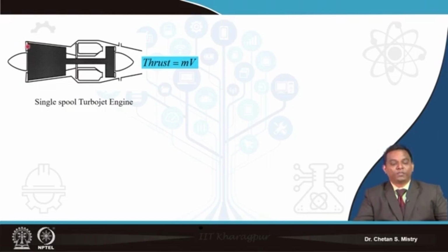This atmospheric air is at low temperature, so you can understand there will be a possibility of the formation of shock at the front stage. Now these shocks act like an aerodynamic penalty, which may reduce the performance and the efficiency of my engine.